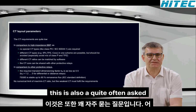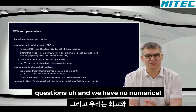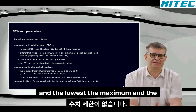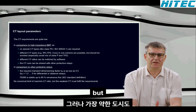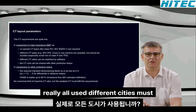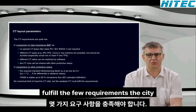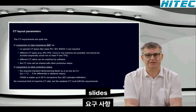Okay, this is also a question that is asked quite often, and we have no numerical limit: what is between the highest and the lowest, the maximum and the minimum CT ratio? But even the weakest CT must fulfill the requirements. That is important, so that really all the different CTs used must fulfill the CT requirements. The CT requirements I will explain in the next slides.